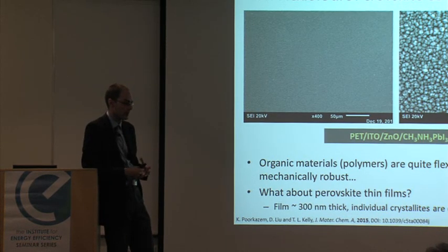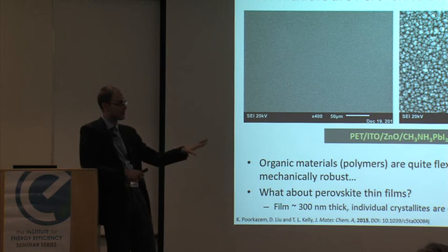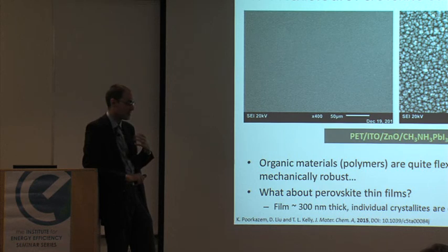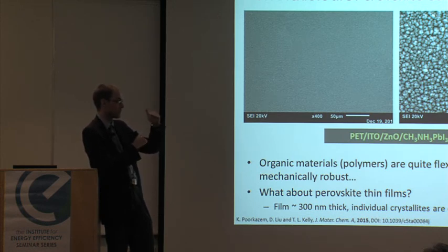Right. Because we would like to put a label on this material and say, okay, it has a carrier diffusion length of 100 nanometers or 1,000 nanometers or 175 microns. The initial studies that were done, the back-to-back Science papers by Gratzel and Snaith, reported carrier diffusion lengths for this material of 100 nanometers. And so for a 300 nanometer thick film, you're pretty much just at the cusp of exceeding those diffusion lengths. So you're starting to get losses due to recombination.